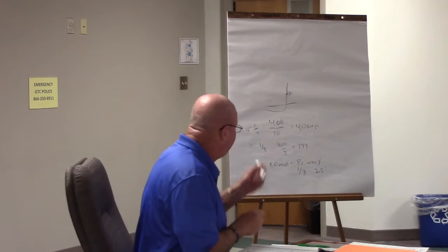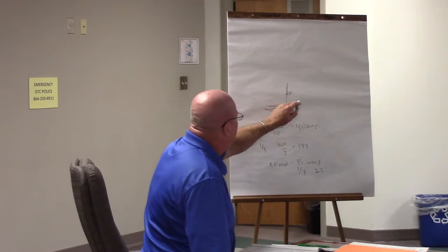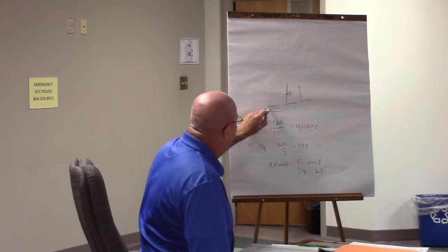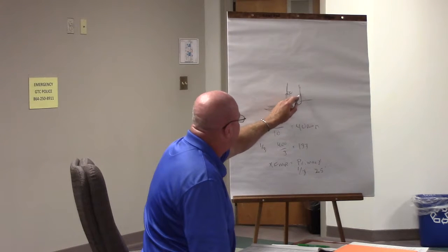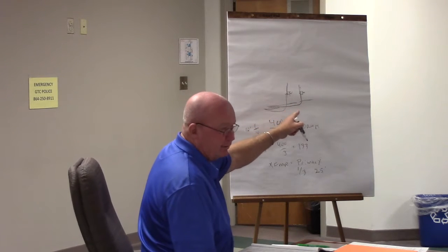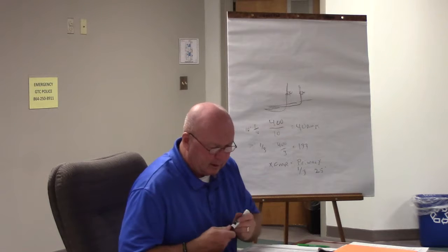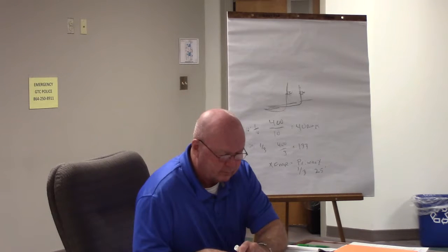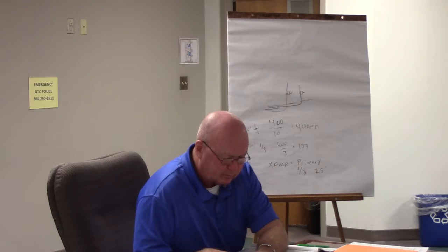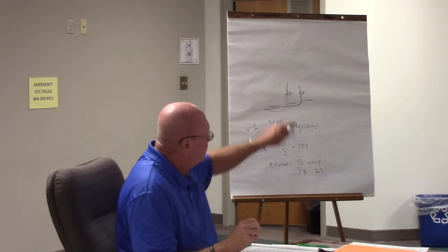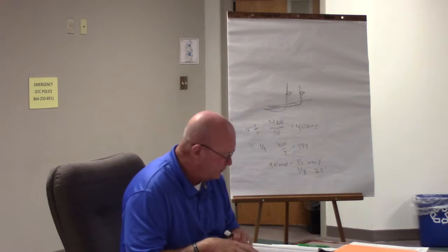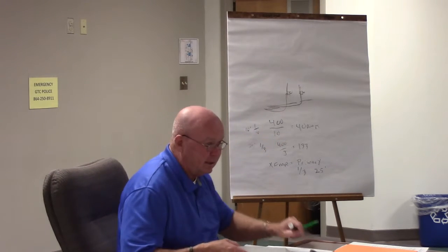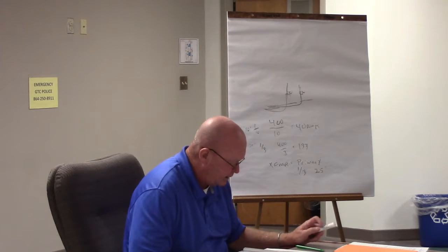In other words, if this wall, if we needed to hit this wall here, we could bring this in and come up and hit the disconnecting means, couldn't we? Because that's considered outside the building. Number 4, we're installed in conduit and under not less than 18 inches of earth beneath a building or other structure. We're installed with rigid conduit, or IMC, used to accommodate the clearance requirements of 230.24 and routed directly through an eave, but not a wall of a building. So there's some exceptions there where we don't have to do this. That's a pretty important code right there for getting us around this direct connection when we turn it. Y'all understand that? Yes, sir.